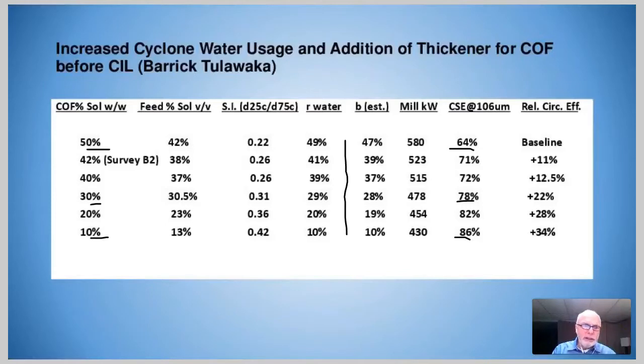Now, you should be considering what is the percent solids requirement of the feed to my downstream process. If you're producing cyclone overflow at 35% solids and adding water to dilute the feed to your downstream process to say 30%, by moving that water back into the feed to the cyclones, then there's absolutely significant potential for improvement.